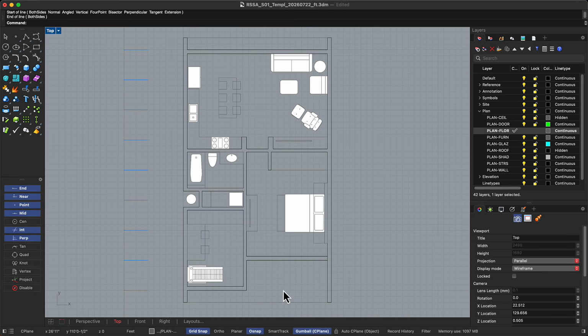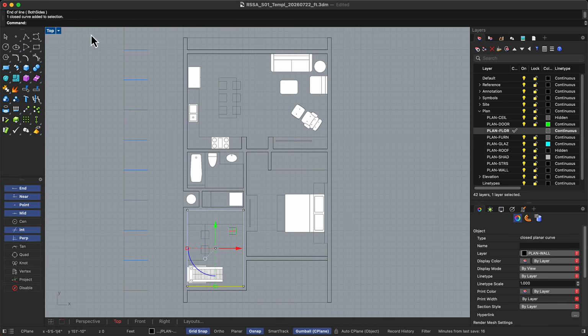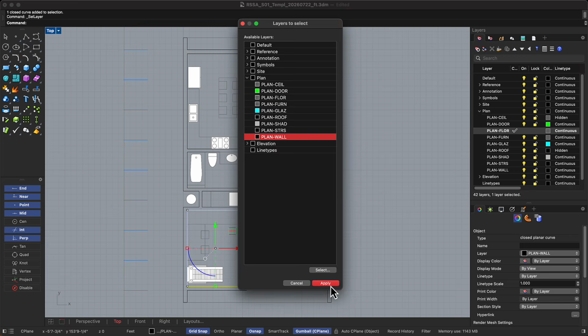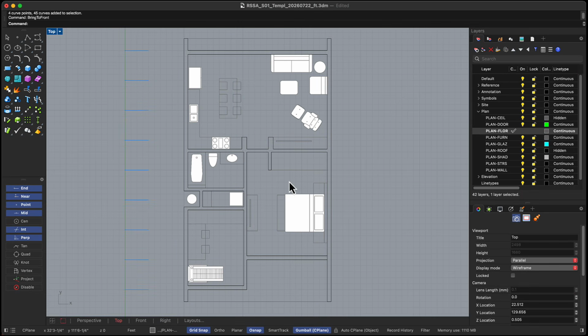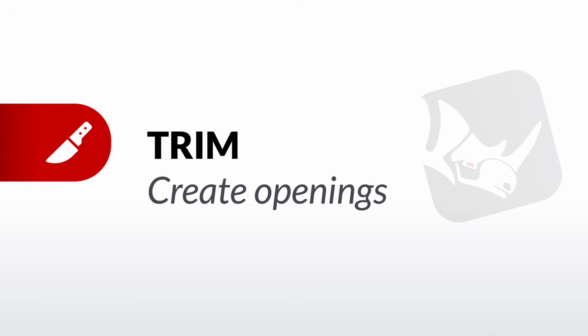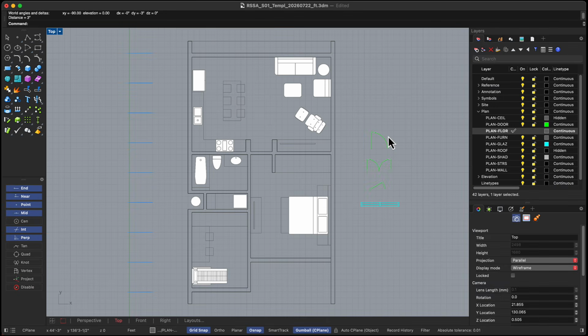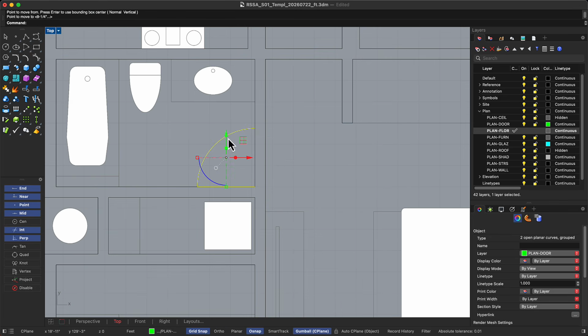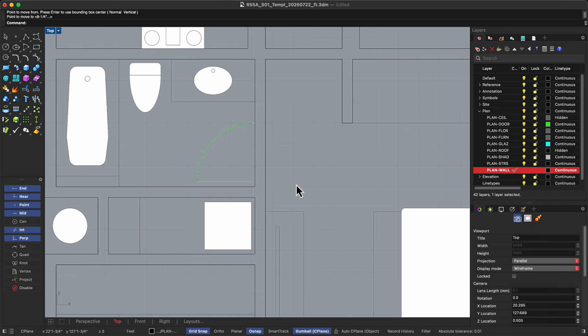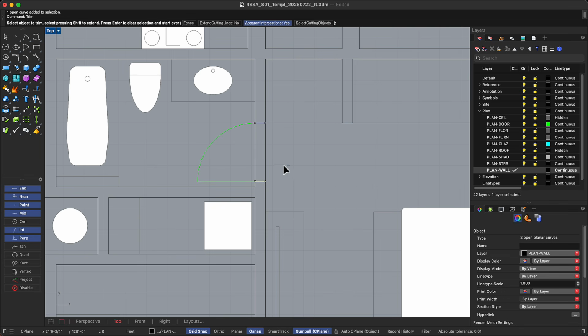The rooms should not only fit their relationships, but should also support the way the dwelling is intended to balance function, form, and emotion. Doors and windows should always be functional, rather than being added wherever there is leftover wall, but balance form and function if possible. Copy the door symbol, draw the two perpendicular lines to mark each jamb, then run trim and remove the wall segments between them, then rotate or mirror it to show the correct swing if needed.